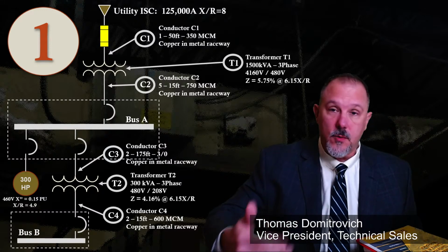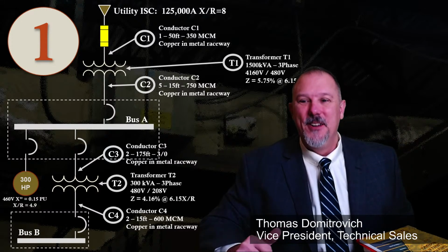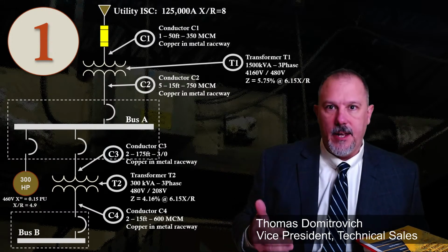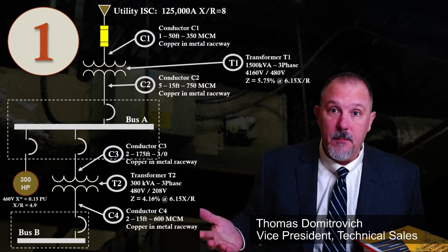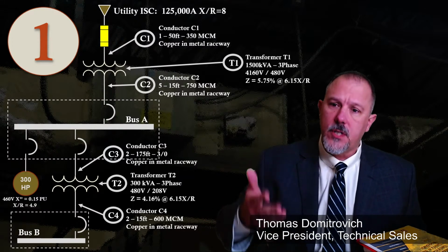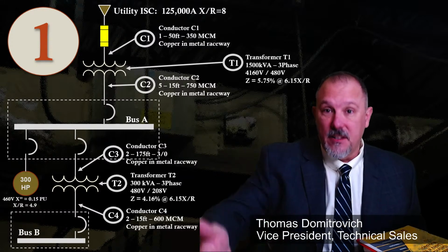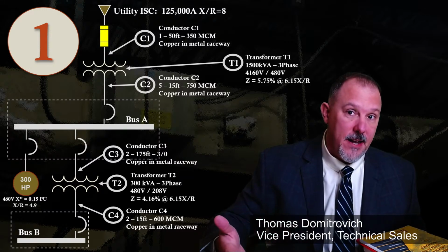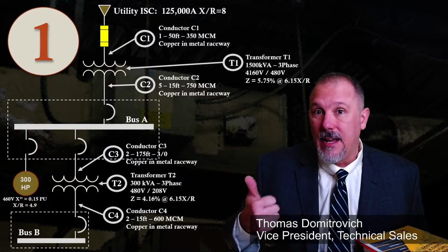So part of my short circuit coordination, and well, this was before Arc Flash was what it is today. But before I could even do my study, I needed to go back to the client and say, I need more money because we're going to have to update the one line diagrams. They've never been updated. So that was just for my fault current calculation and my selective coordination study that I was doing. Now throw into the mix an incident energy analysis. Okay, when your power distribution system changes, you need to keep that one line diagram updated.